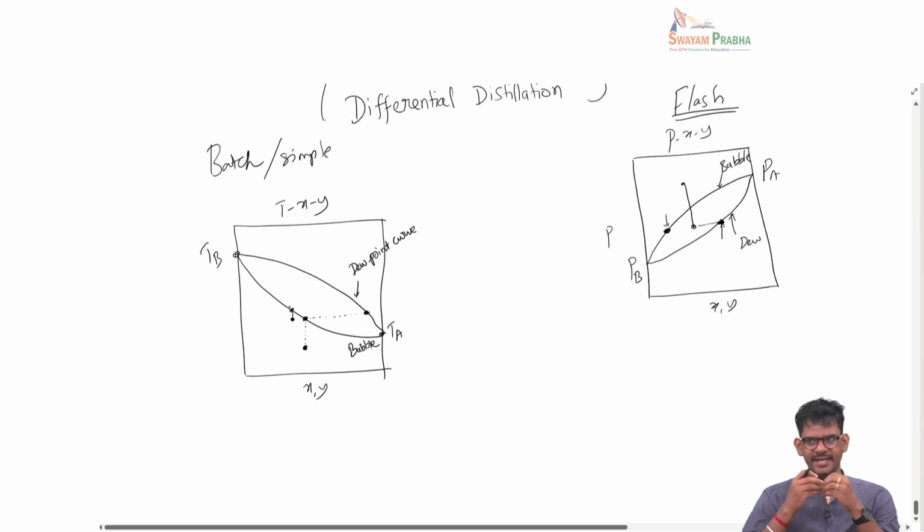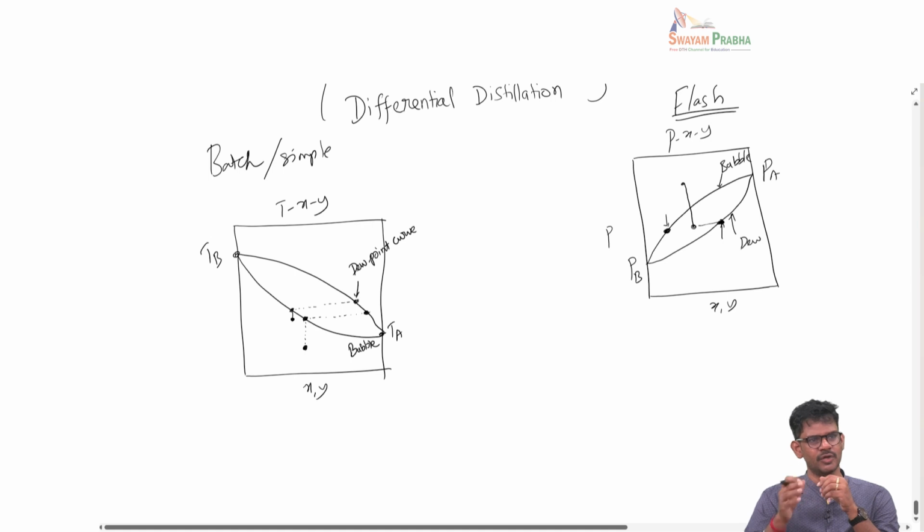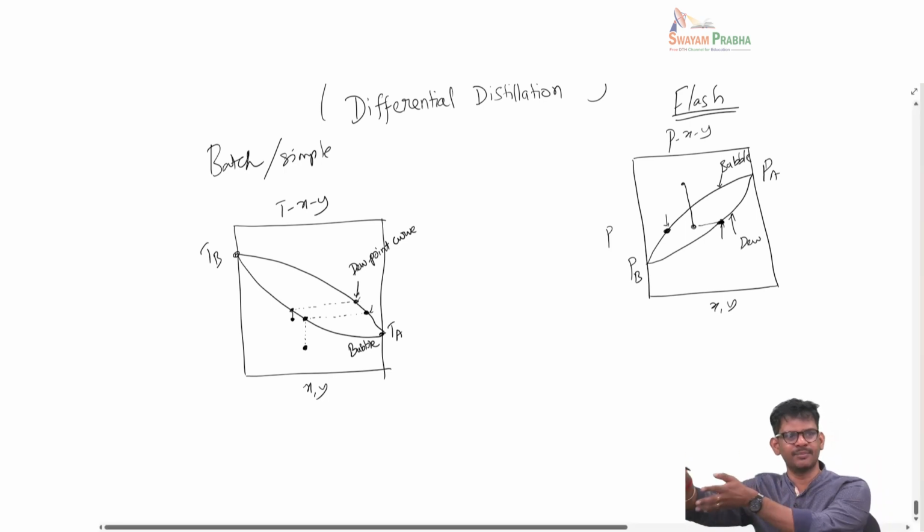Okay, so we are adding a little extra heat, and then what happens is we are reaching a new bubble point. At this point, we will establish another vapor formation because of flash. Let's say here also I am taking this vapor away and mixing it with the vapor that came before. So I am collecting it. I am taking this vapor, putting it in the container. The next fraction, when it comes here, I am collecting that vapor, condensing it and putting it back into the reservoir.